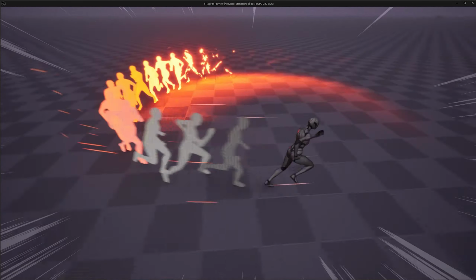Thank you very much. So first we can make the Niagara system. For that, right click, then click on Niagara system. Then we can create an empty one. Then click create. Then we can call this NS sprint. Then open it up. And here first we need to have the trails. So for that we need to create ribbons.